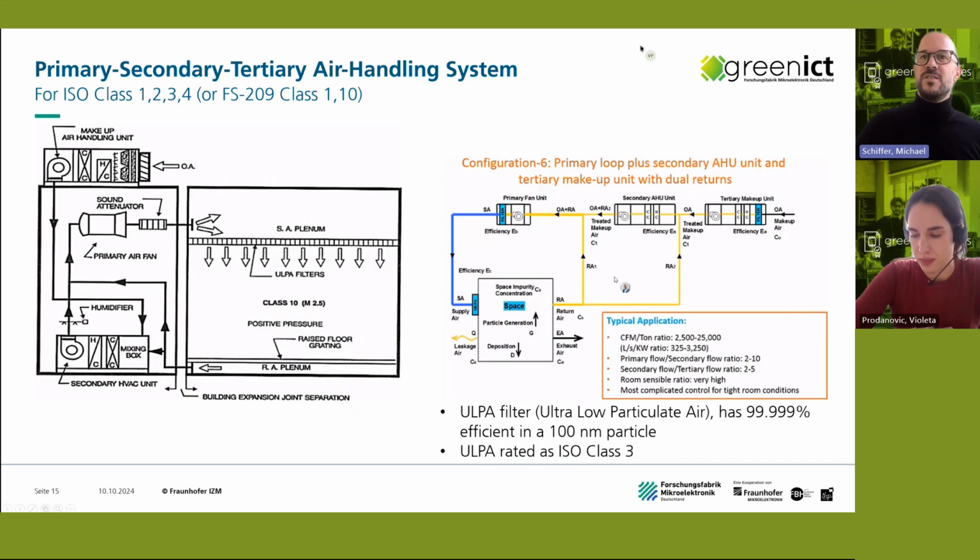And in such systems, when you have complex air supply here, you will see that you also have the return air that will go into the fresh intake in several stages, to really minimize the fresh air you have to take in from the outside.